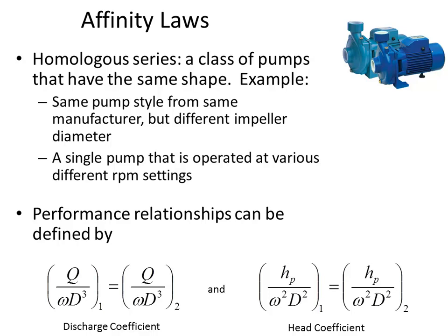And you can put in the system curve and the pump curve into these relationships and the corresponding characteristics of the pump, like what the pump's diameter is. And then you can find out for a certain rotational rate what the pump head is going to be for this other kind of pump.